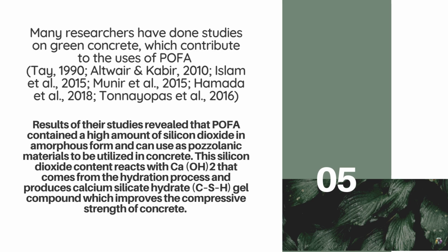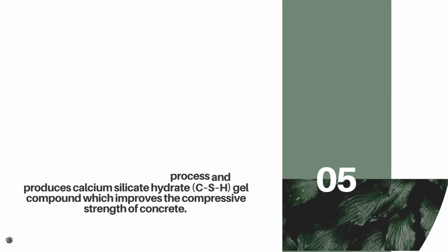This silicon dioxide content reacts with calcium hydroxide that comes from the hydration process and produces calcium silicate hydrate, CSH, gel compound, which improves the compressive strength of concrete.